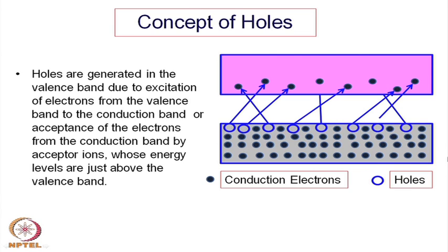This is the band gap, the energy diagram for the host material, in which we have added some impurity, and that impurity may have a very strong affinity for the electrons. So, it has a tendency to absorb electrons, then that will absorb electrons from the valency band and also will create holes.